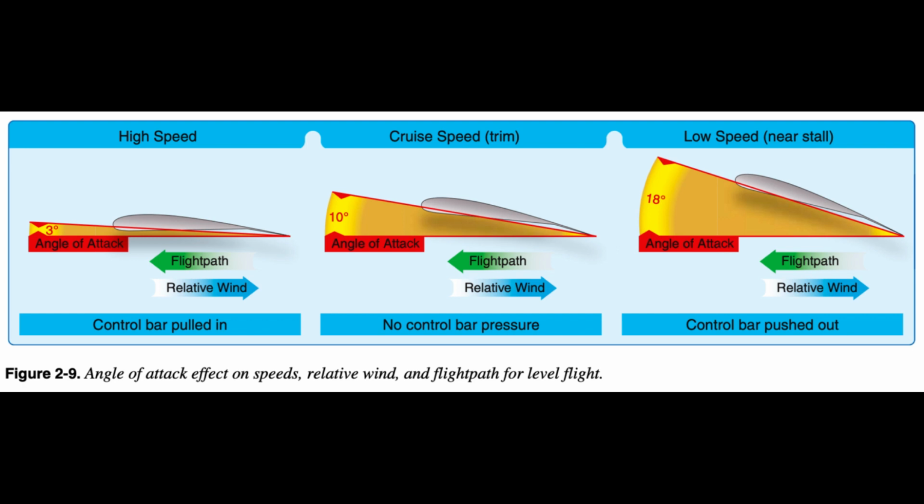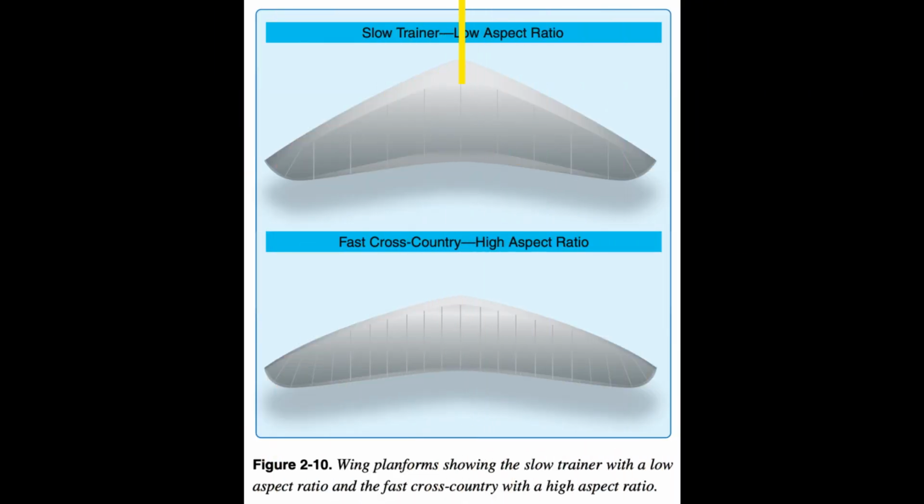This relatively low aspect ratio is less efficient at producing lift. A higher performance wing with 140 square feet, a 35-foot wingspan, and an average 5-foot chord would have an aspect ratio of 7. The WSC wing is similar to airplane wings in that the aspect ratio differs with the specific design mission for the aircraft. End of page 2-5. For the same wing area and similar design, the lower aspect ratio wings produce less lift and more drag, higher aspect ratio wings produce more lift, less drag, and may require more pilot effort to fly, depending on the design. Figure 2.10.